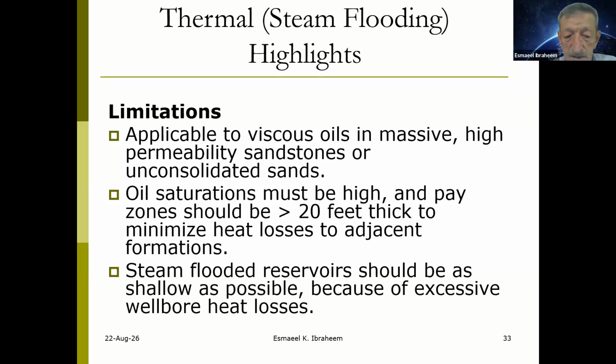Also, one of the limitations is that steam-flooded reservoirs should be as shallow as possible because of excessive wellbore heat loss. This is another point, as we may have described before: we don't want to lose the steam temperature to the other formations. That's why we need shallow wells, so the steam takes less time to reach the oil.